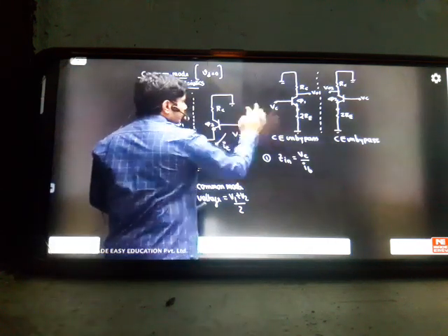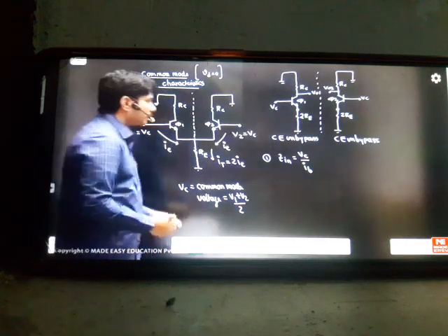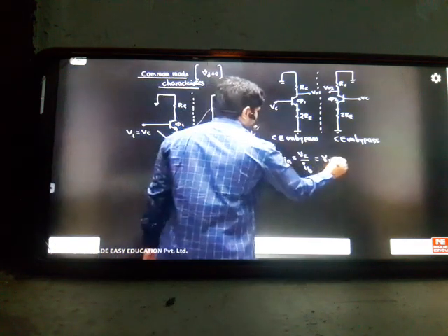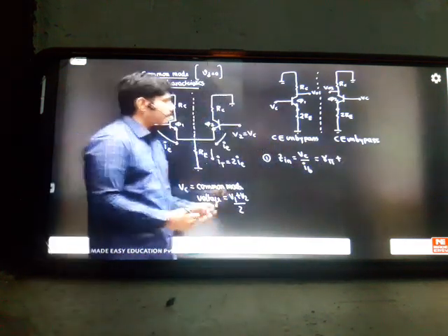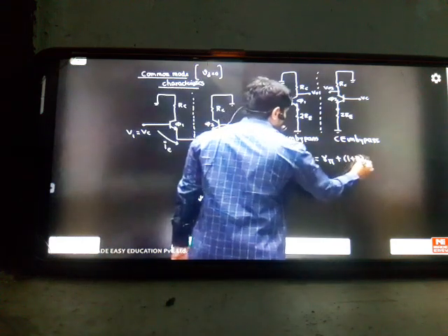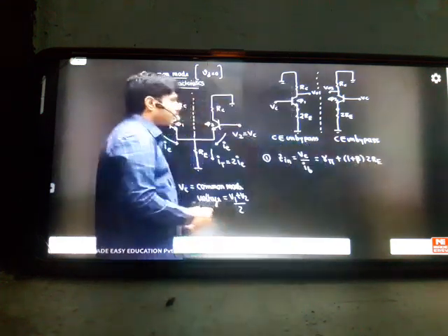Seeing the board, you can tell the answer, which we have studied in our BJT classes. What is the answer? Seeing the board, it is simply r pi plus, in the style of writing, you will have r pi here plus (1 plus beta) times 2 RE. So this is the backup knowledge we have from common emitter unbypass techniques.